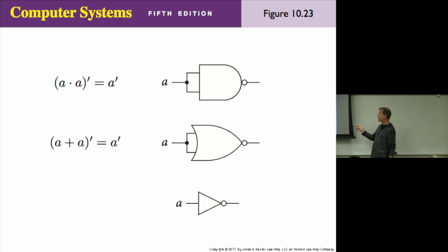And furthermore, because of this NAND and OR thing, you can do anything with a NAND. The NAND is all you need. What does it talk about, tying unused NAND inputs to VCC and unused NOR inputs to ground?